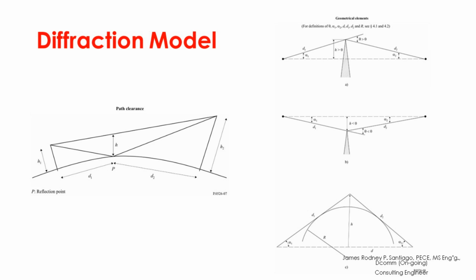The models are applicable to a variety of obstacles and various path geometries, which means the varying terrain, the size, the bulge, to be used in the calculation of field strength over the communication path, which includes a spherical earth surface or irregular terrain with different kinds of obstacles. So when they say obstacle, sometimes we call it, in basic communication theory, the height above average terrain.